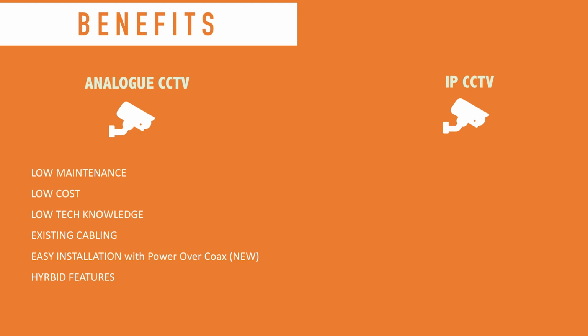The other advantage you have is there's actually a new system known as power over coax. That means you would not need to run the shotgun cable. You can run a single video cable. So have a look out for POC, which has been around for a very long time, but we're seeing it creep back up, and that's because the manufacturers have found a way to send high definition signals over a single cable. And the other advantage there is you can run up to 200 meters, so where previously you were restricted on power up to about 50 meters, you can now run up to 200 meters.